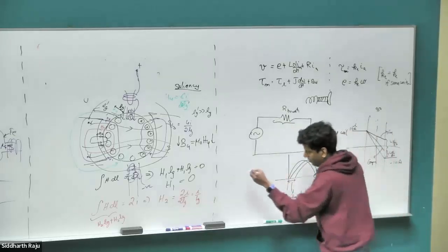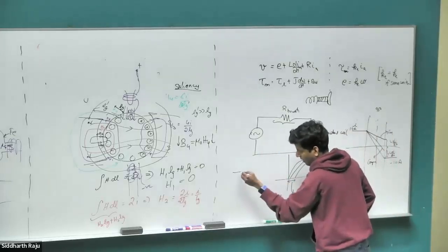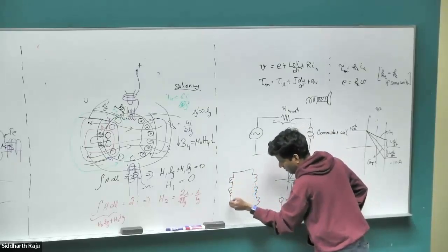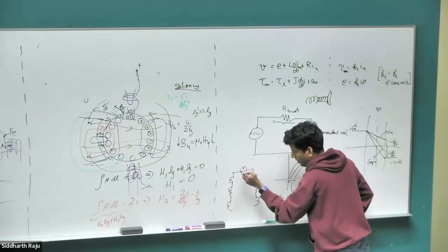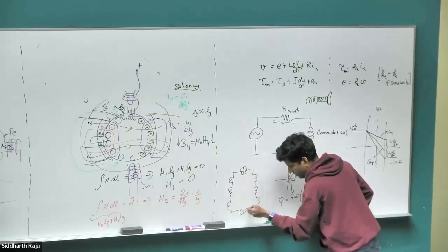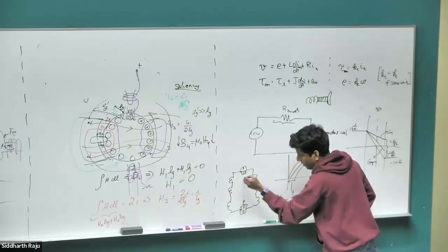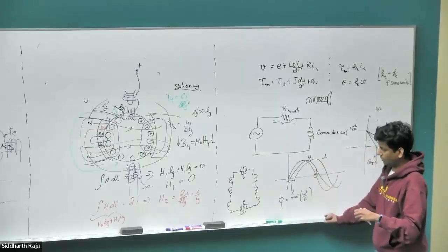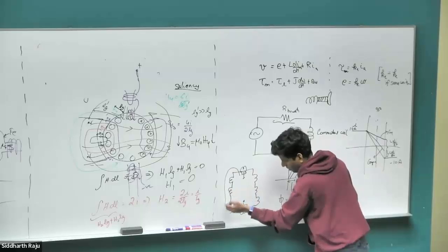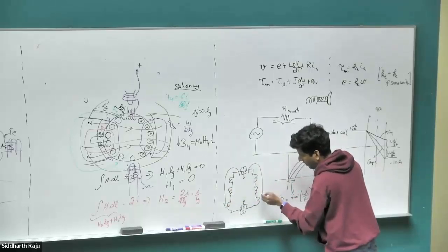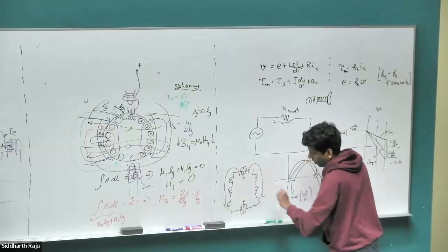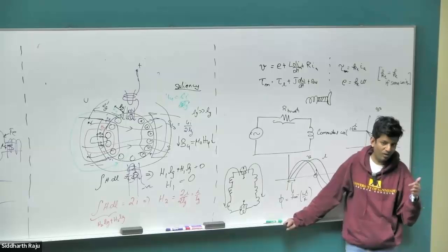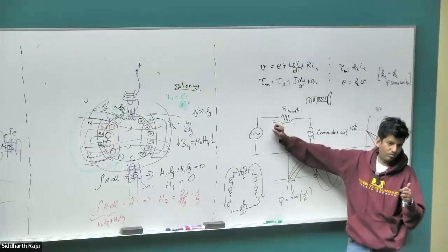So if we had a graphite brush, the current not only flows, so when we had our equivalent circuit diagram that we drew, let's say there is a commutating coil, and this is what it was shorting. For the coils that shorted, having this large resistance was helpful because the current was in phase with the voltage. But for the coils otherwise during normal operation, for coils that are not commutating, or in the case where this is shifted around and none of the coils are commutating, the current is still flowing through this graphite brush, which has very large resistance, right? And then I squared R losses become very large, and a significant amount of power is lost in the brushes.